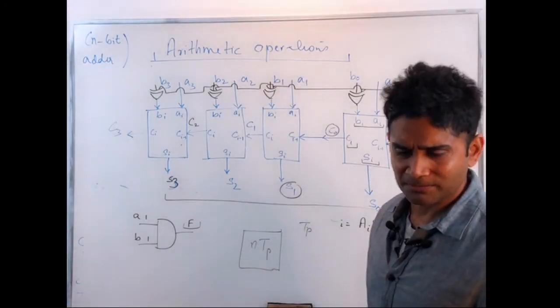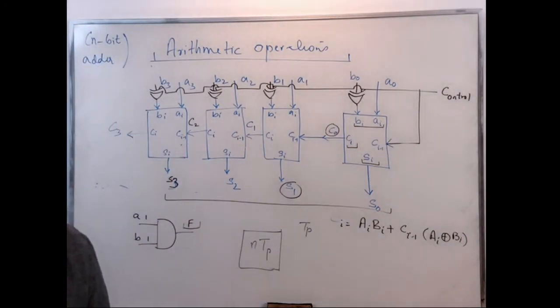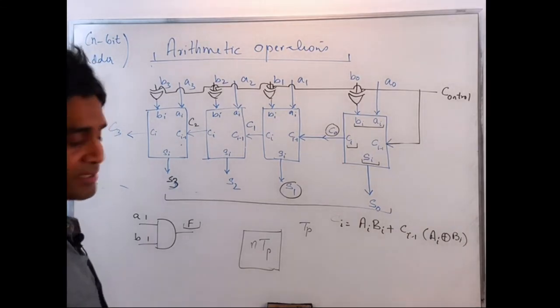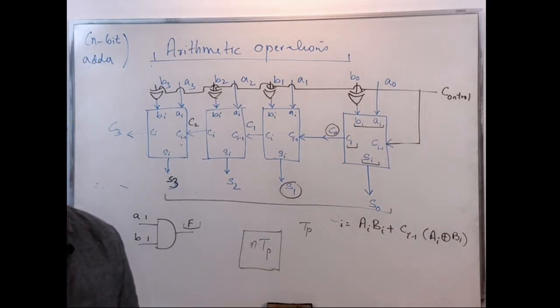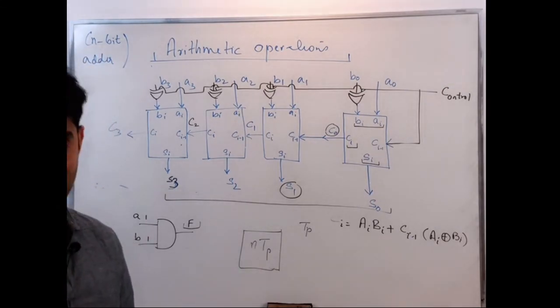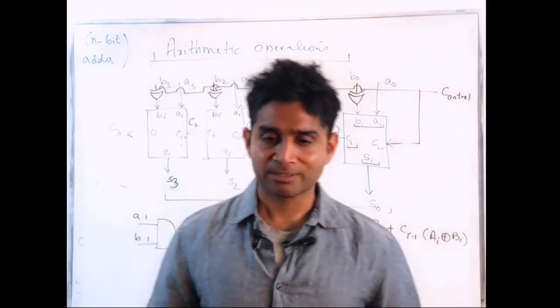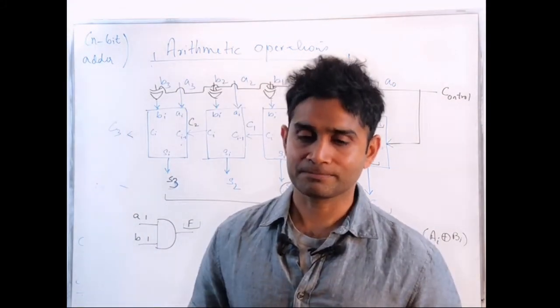Does it make sense? So again, this is something you need to be cognizant about. You cannot just indefinitely add modules to it and expect to get the correct sum right away. You will have some delays there. It has to go through a sequence of transitions until it settles down on the right value.